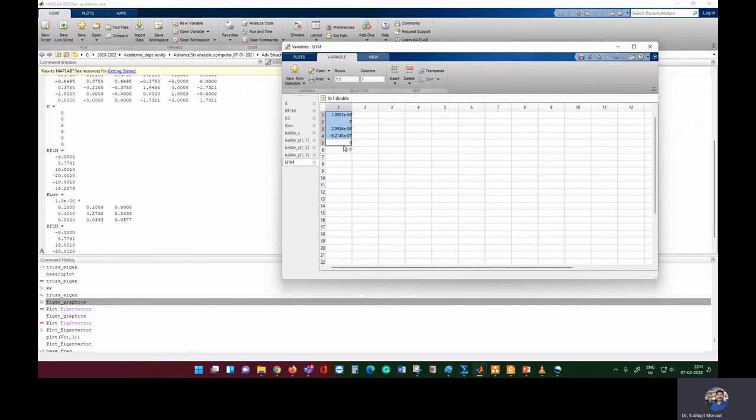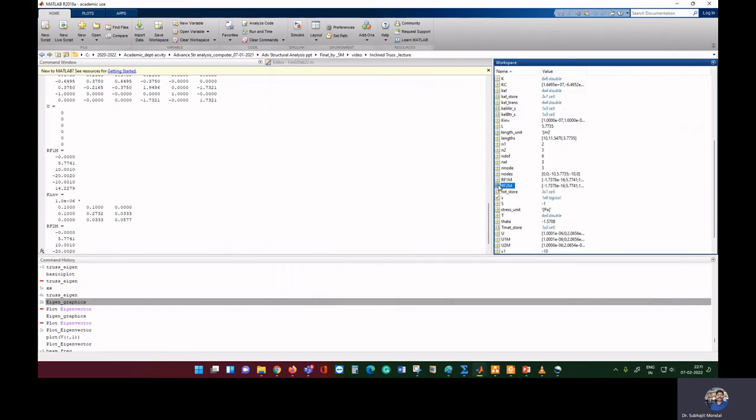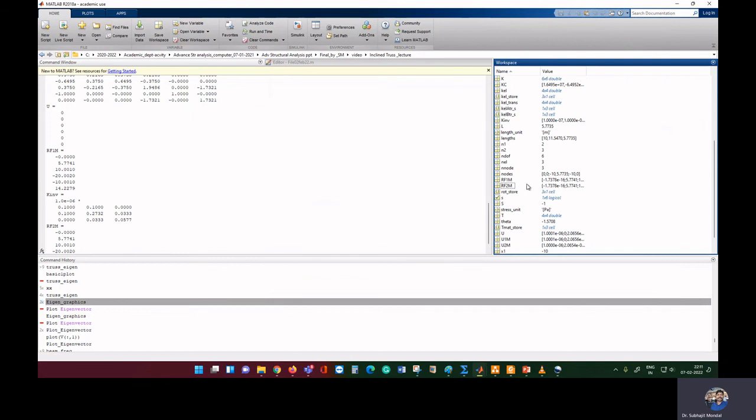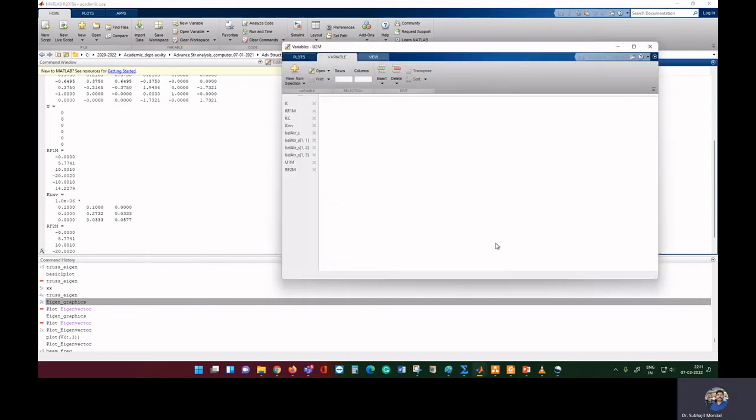Here you can see this value, obtained using the method where we added stiffness on the diagonal terms. Okay. Now if you see the solution from the other method, you can see this part is 0. So this is for reaction force. So you have to find it for displacement term, this one.